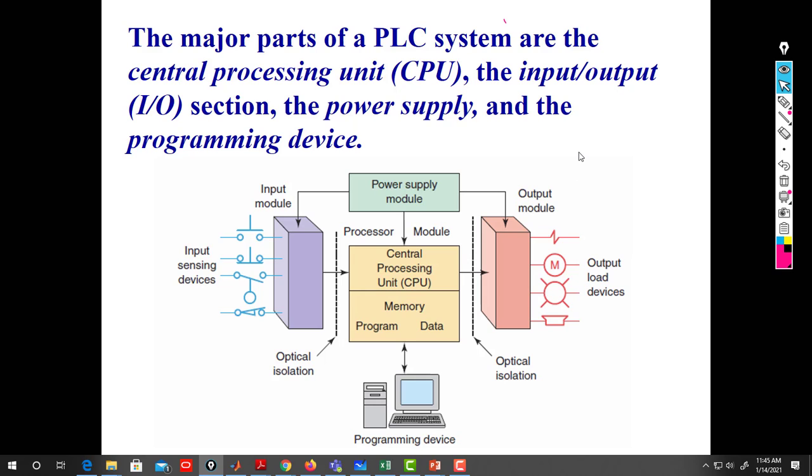So in an open architecture, usually you can replace maybe the input module by a different module from different places, so it's open. Maybe you can replace the CPU, replace the power supply, etc., from different manufacturers, from all the available manufacturers you have. So it gives you a kind of flexibility in changing things, and the architecture is all clear.